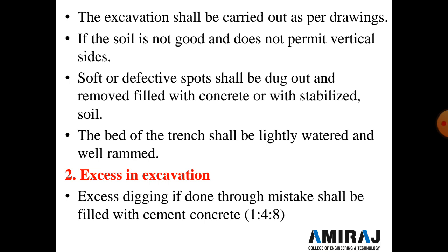If the soil is not good and does not permit a vertical side, the side should be sloped back or protected with timber shoring. Soft or defective spots shall be dug out and removed, and filled with concrete or stabilized soil.